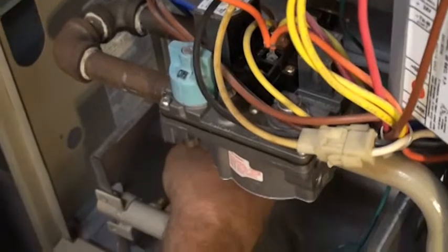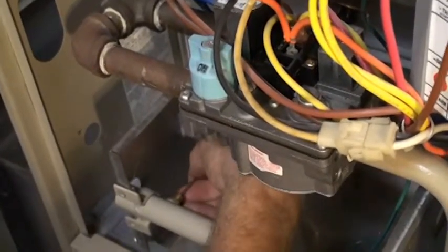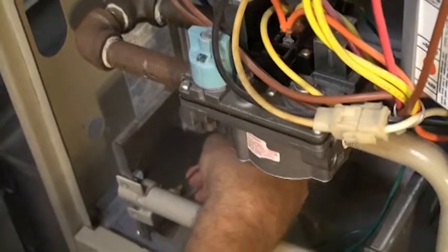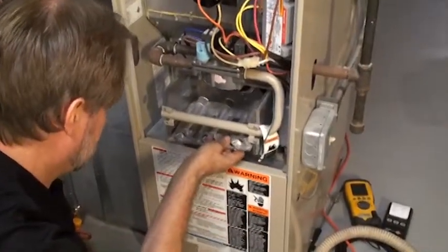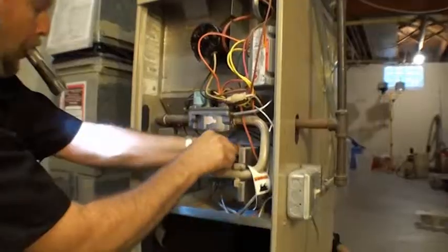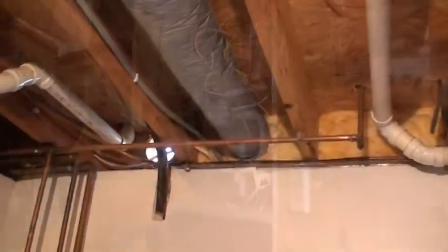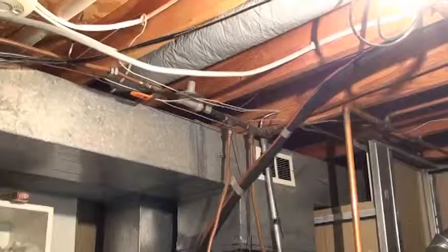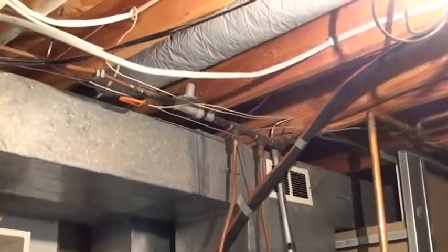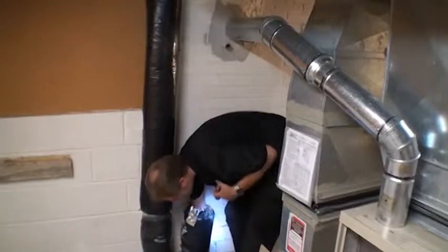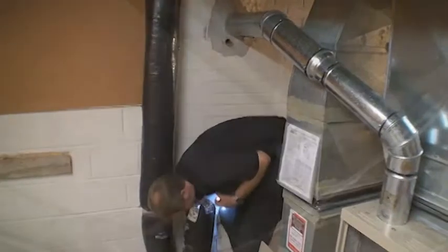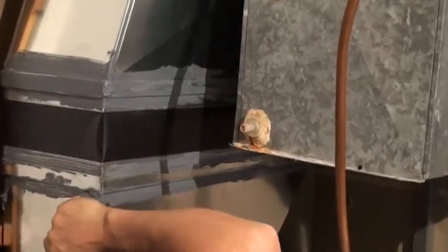Check that each orifice is cleaned and correctly sized for the designed furnace input. Reinstall the burners and igniter assembly. If there is an existing combustion air tied into the return duct, remove it. For existing combustion air, clean the hood outside, put in the J-trap, and ensure there are no obstructions. Seal all accessible ductwork with duct mastic, including all duct connections, gaps, and holes.